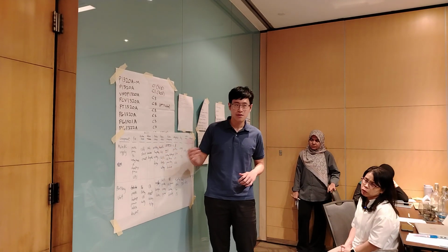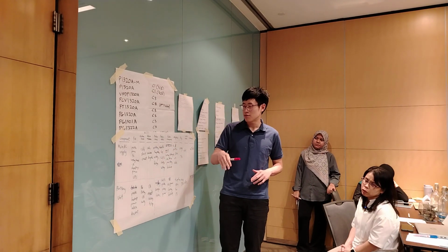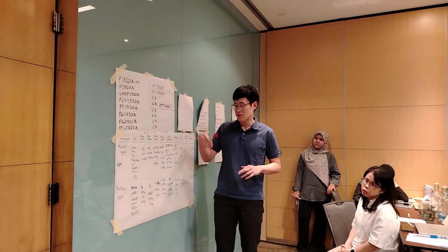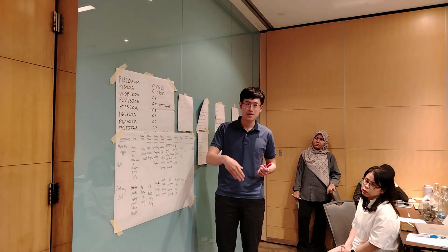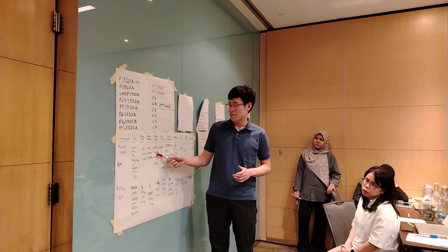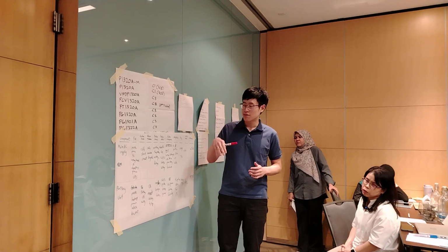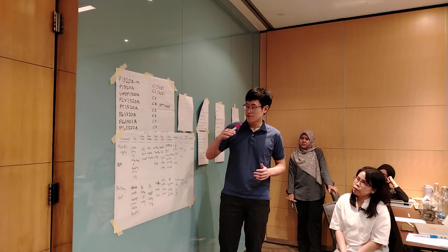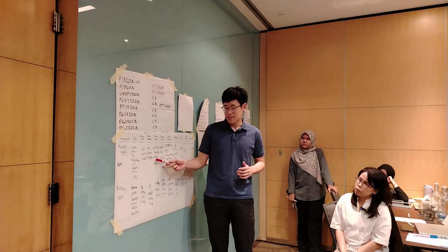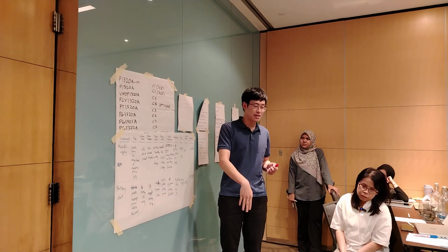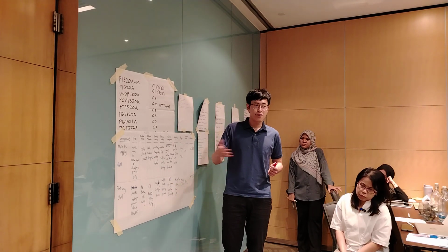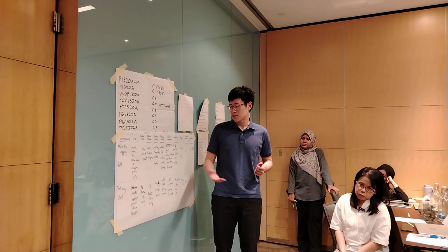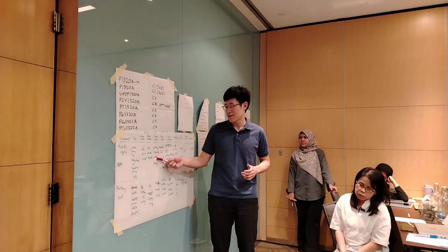Probably moisture, where water ingress into the cable causes electrical sparks and eventually the short circuit. Or temperature, where the cable has over-temperature for a prolonged period, causing the insulation to degrade over time. And acidity, because the cable is underground, so there is acidity in the soil causing degradation again.